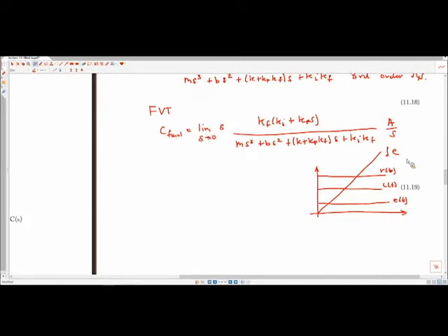Agreed. So there are ways around that. It's called anti-windup control. It's not something that we're going to talk about in this class, but you talk about a buffer, right? So there are ways to handle this where you're continually subtracting out that integrated error if you observe that you run into some sort of wall or something like that. So people figured out that problem too, somewhat, but yeah, that's a big problem with integral control. We'll talk about some of the more basic. That's a more complicated problem with it.